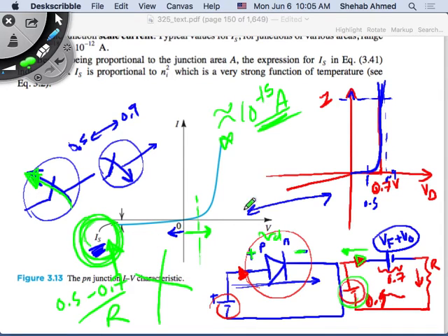But do we see now how this is operating? Abdulaziz? Yes. Okay, so theoretically speaking, if I make this resistance a short circuit and I make this source 1 volt, then current should flow equal to 1 volt minus 0.7 divided by 0, so it's infinite current. So theoretically, this model will allow infinite current to flow.